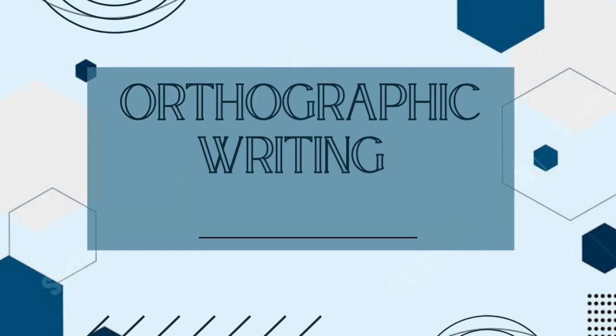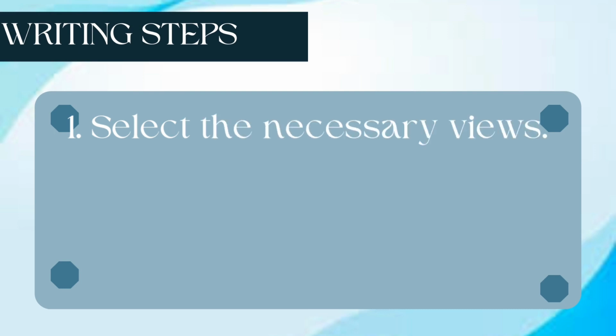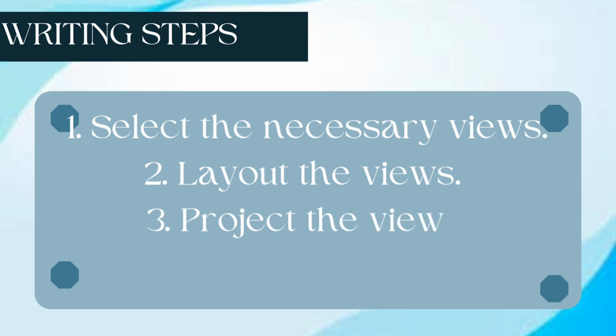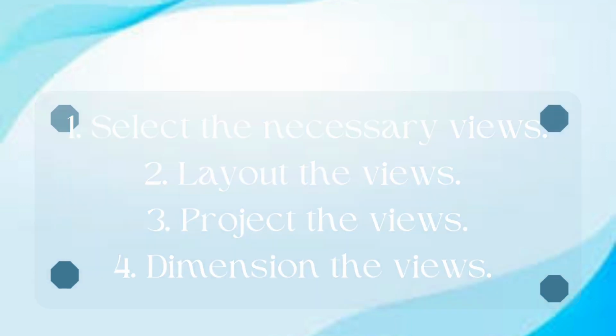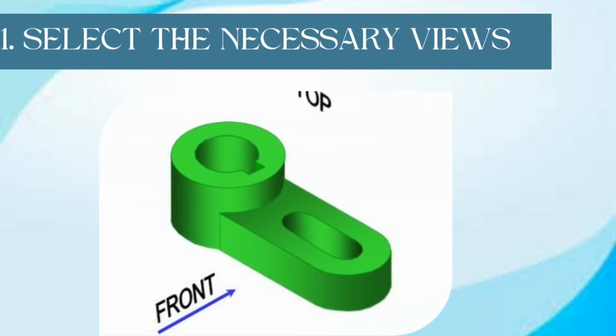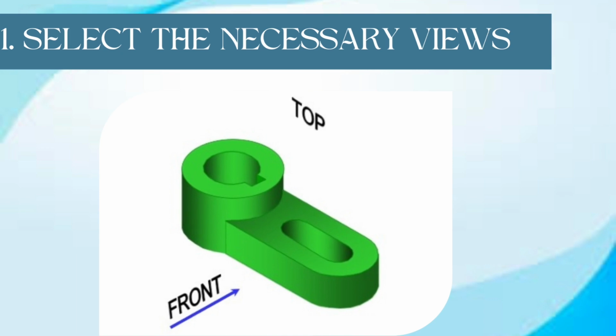Next are the orthographic drawing steps: select the necessary views, lay out the views, project the views, and dimension the views. Select the necessary views. There are multiple options.